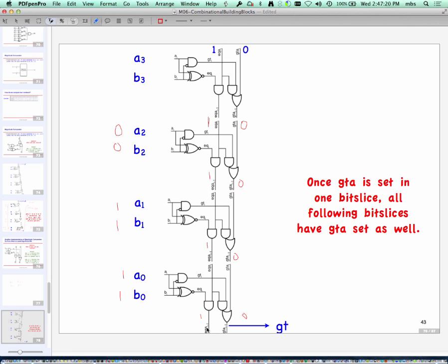If I want to say, give me less than, A less than B, then there are 2 ways of approaching it. One is I just swap B and A, I just rewire the circuit differently, or the other is I put some negation logic at the output.